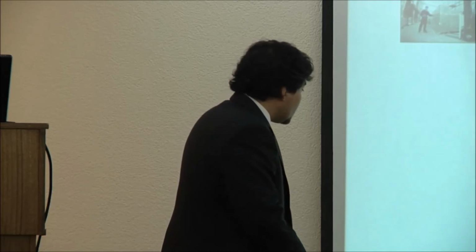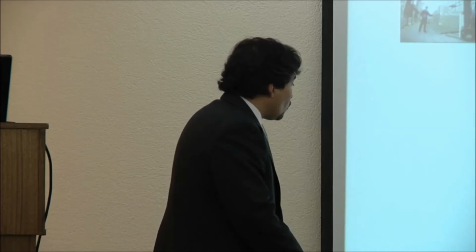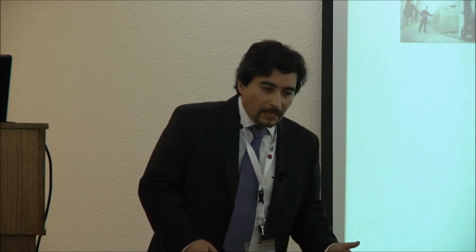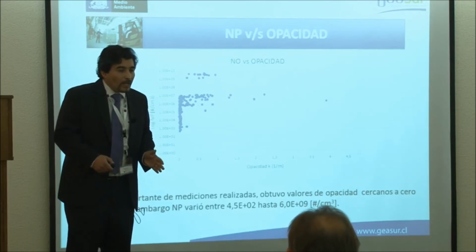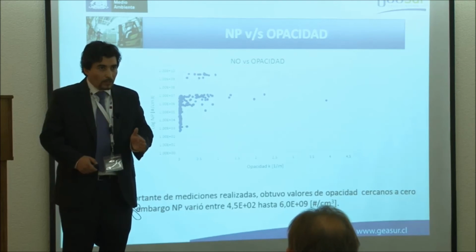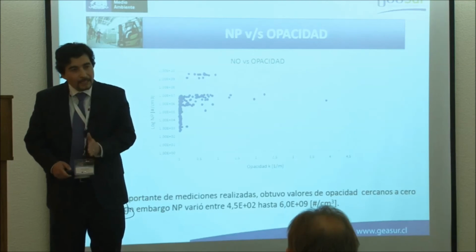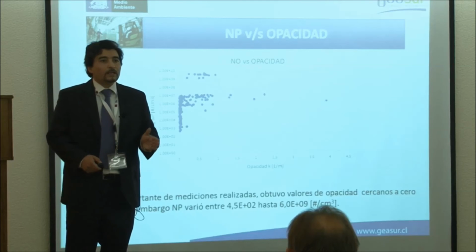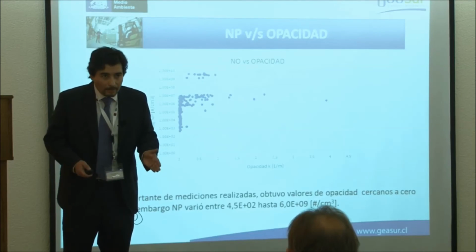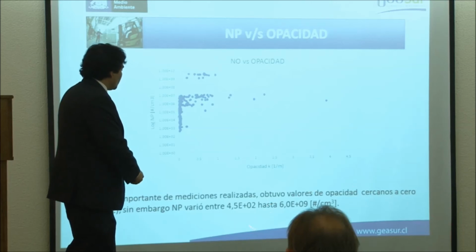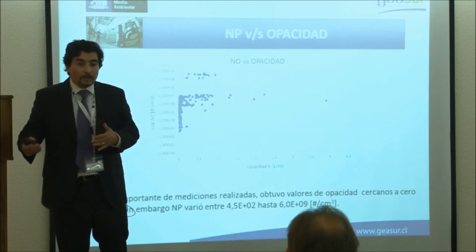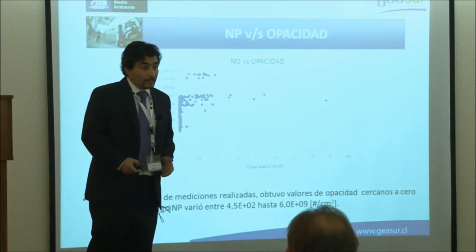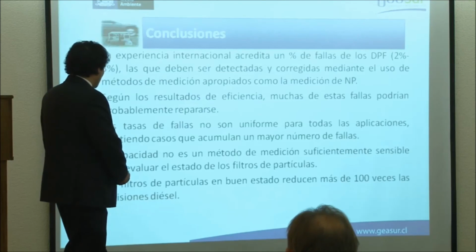I want to clarify also that these were the values reached by buses without filters. And we should put our attention on the fact that if somebody is going to measure a value over the exhaust pipe, we have to consider that the filter has an efficiency. So if we have these levels of number of particles in the engine, probably there is also going to be a high concentration at the output of this filter.